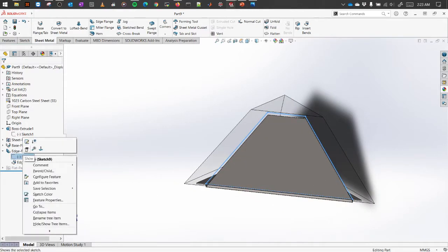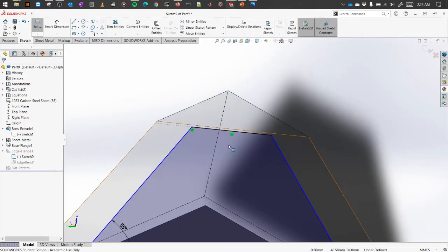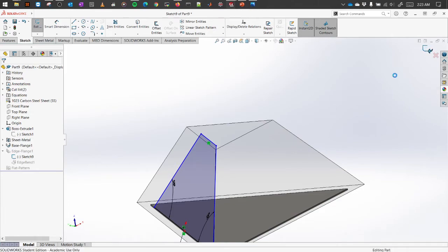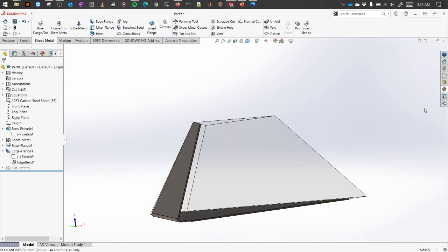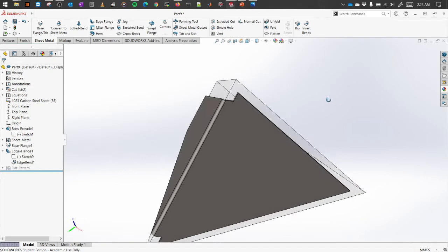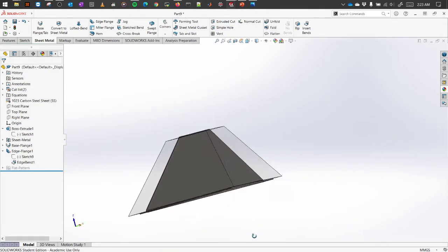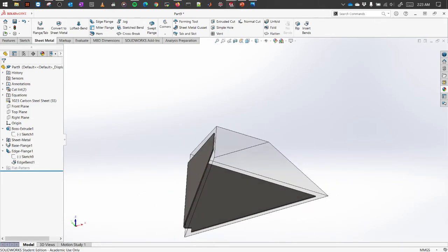If I hadn't added that, okay, let's go into the sketch. If I hadn't added that collinearity constraint, which was this one, if I delete this, you will see it has again risen to the height. So depending on how you want to use it, you can add this constraint. Okay, so we can do something similar to all the other three sides.